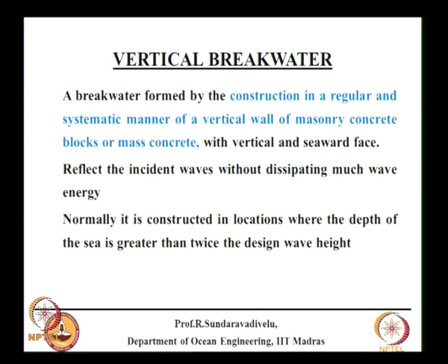When we discuss the breakwater, the energy comes from the waves formed by the wind. Whenever wind blows over an area of the sea which is called the fetch, and for a considerable duration, the wind transfers energy into the sea, which creates the waves. The waves are created when the water surface goes up. Due to gravity, waves come down, which is why these are called gravity waves.